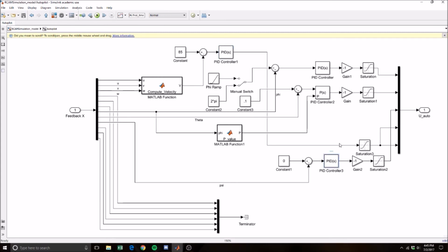So I have all these controllers which are controlling everything, and I'm telling it I want my rotational angle about my x-axis, which is the longitude of the plane, to rotate to 2 pi, which means to do a 360 axial turn, and then it's going to stay there. And that's what it does, and that's what you guys saw in the video.